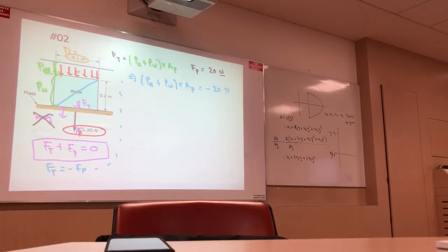Alright. They tell me to please find the pressure of water. So pressure of air, what is water? Rho G H. What is the value of H? 0.2, right? Is equivalent to minus 20. What is the area of piston? Pi by 4, right? Times diameter 0.1 squared.